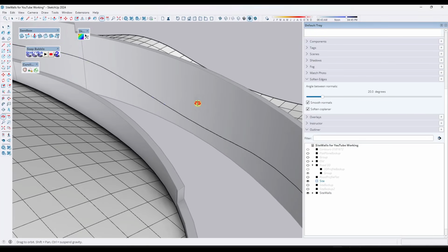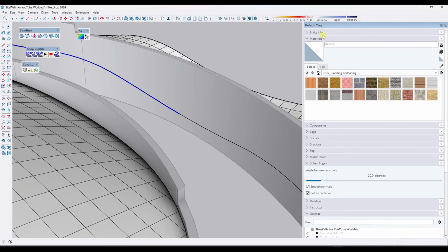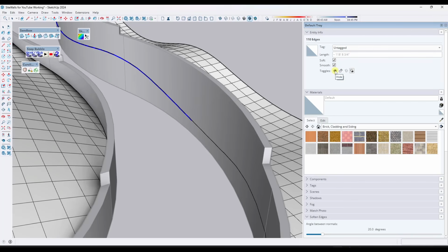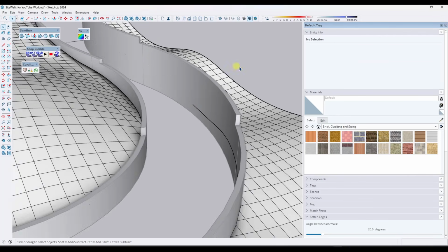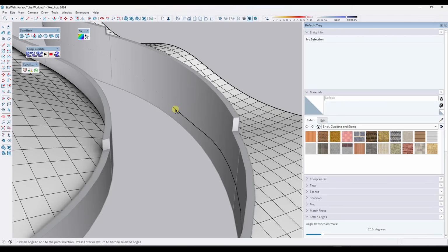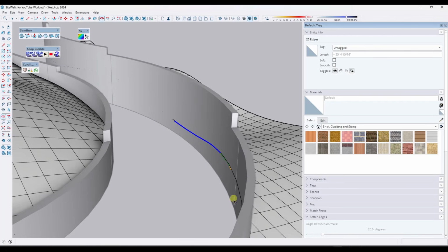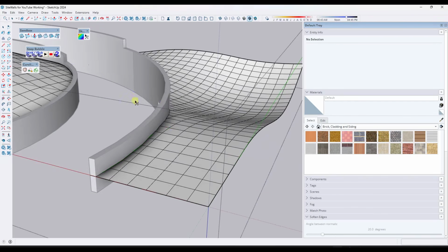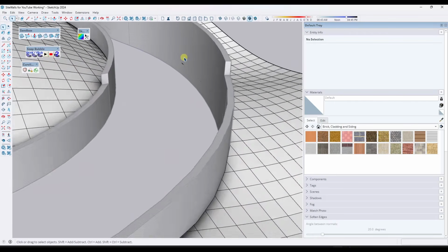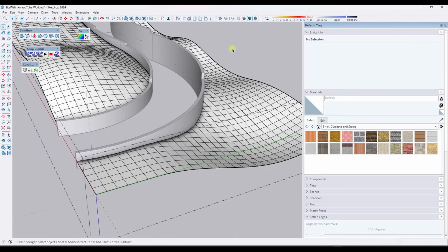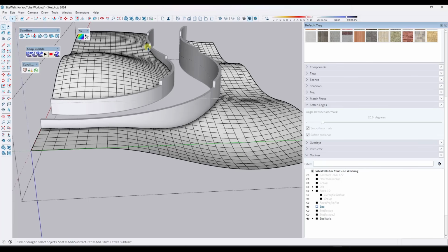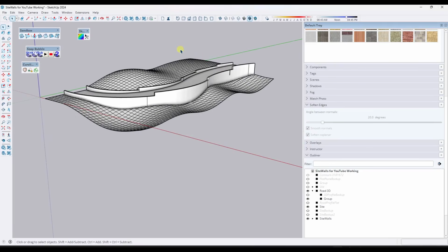And sometimes it can act a little bit funky, so you might just want to take this selection. But what I'm going to do is toggle hide. And what that's going to do is allow me to hide the edges that are in there. So I'm just selecting those edges using this tool like this, and then we'll just toggle those edges to hidden. So then you don't have to actually erase out anything in here. You can just hide those edges. And in this case, it doesn't matter because that's going to be under your road, but on this back wall, sometimes it matters. So that's another way to hide this without destructively editing your walls.